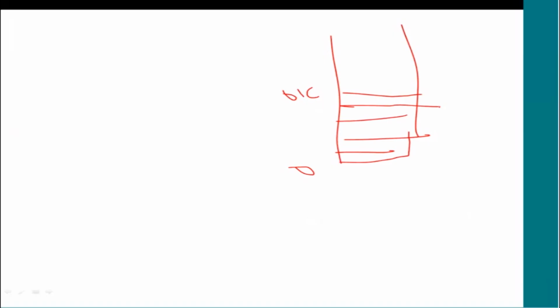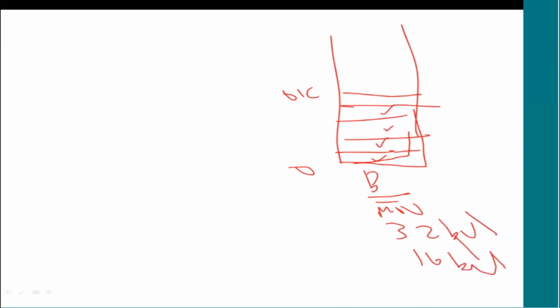As a programmer or as a system developer, you have to fill in some instruction here. Agree? So for that branch instruction or move instruction, whatever you are putting, you have to decide whether you are going to put a 32-bit or 16-bit one. Because if it has to be supported in Thumb mode, you have to put a 16-bit instruction. So when you have only one place, you have to put the branch instructions here based on which interrupt is happening.